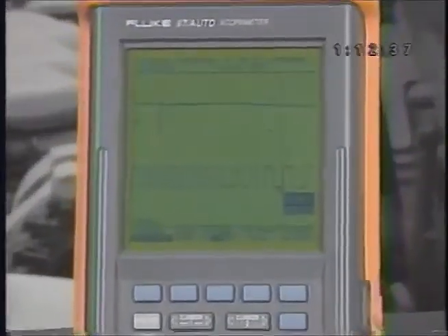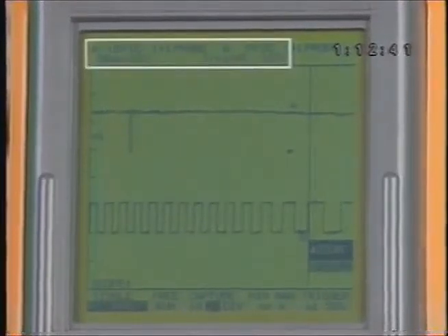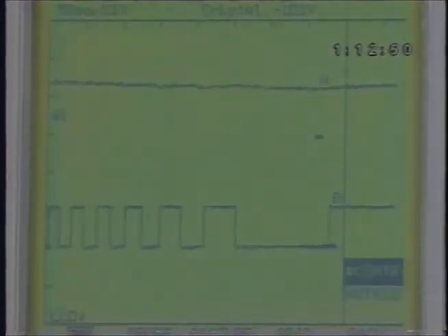Increase the time base to display 3 to 4 injector pulses. Trigger on A with a delay of -1. When the injector signal drops out, the trace will continue to the end of the display and stop. Since free run is off, losing the trigger forces the display to show the last waveform trace.